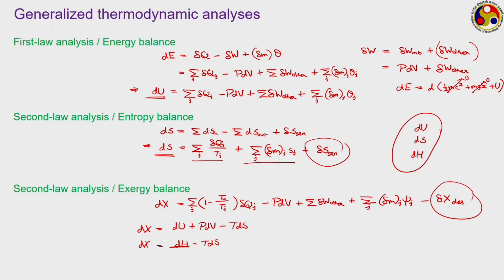However, the basic balance equations of thermodynamics we are getting not in terms of those properties, rather in terms of these three: the changes in internal energy, enthalpy and entropy, but none of them can be measured directly. And that is where we need to develop certain property relations where we can represent the change in these parameters in terms of the measurable parameters.